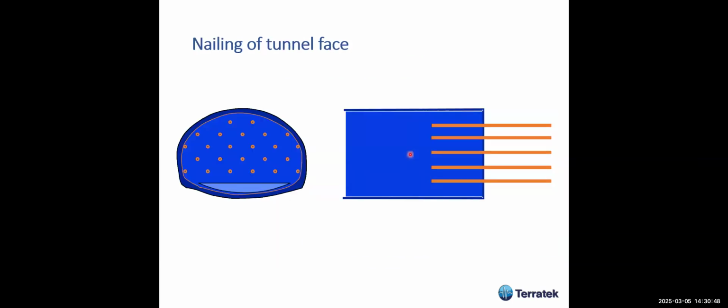And this is not related to slopes, but this is a very good solution where we must use these FRP bars: nailing the tunnel face, okay? When you do that by nailing, it's very easy to excavate. If you had done it with steel bars, it would be a big problem. I have used this in a few tunneling projects, and it was very successful.